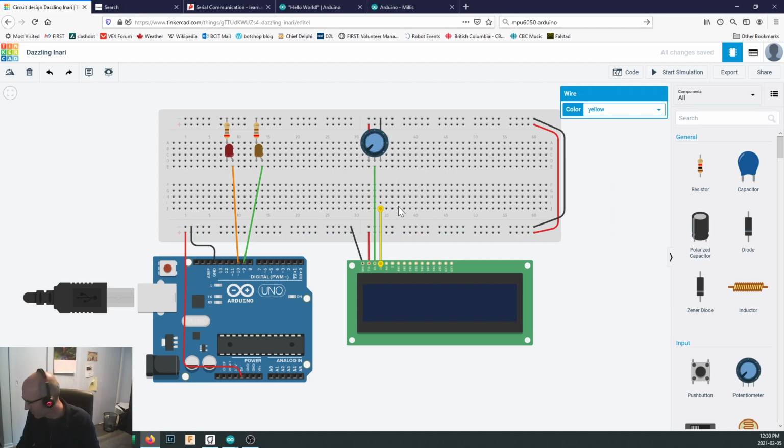And so this yellow line comes in right here, and then we're going to run it back to our Arduino back over here. And our yellow line is going to come in and plug into pin 7 on our Arduino. You can bend that around, and let's just make that yellow. Now, what this is doing for us is this is letting the Arduino send a signal down here, and it's going to be part of our parallel communication circuit and how this talks to the Arduino.